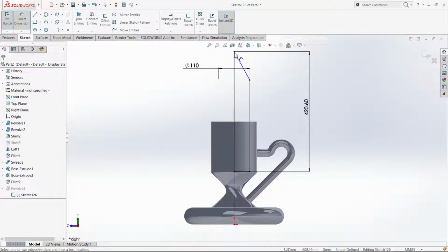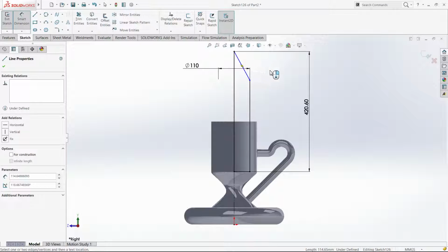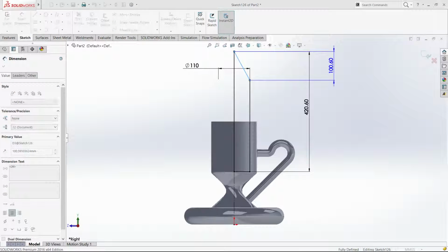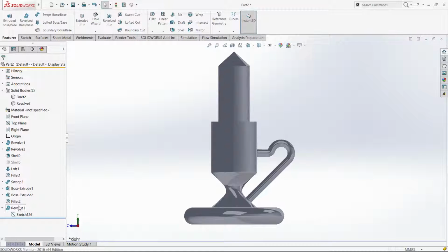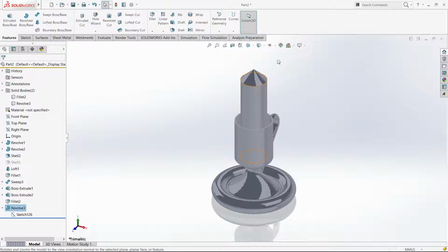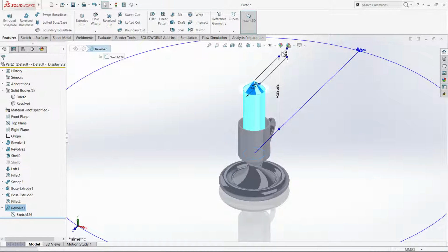and say from this point, well, I'm gonna select the line and go horizontally to the right or left, and it's gonna give me the height. And I'm gonna say this is 50. So now whenever I drag my new dimension, it's always gonna be the same on the top. So that's something that you have to take into account just to make your life easier and not have to change a bunch of stuff just to get the same end result that you wanted before, and get in your calculator and try to subtract whatever you want.